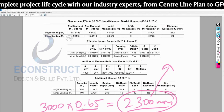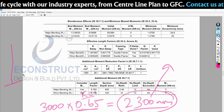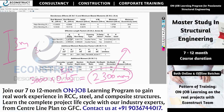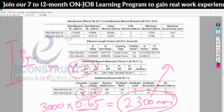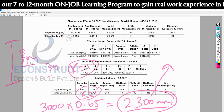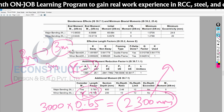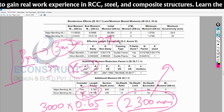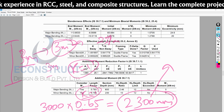Now consider the K value. In any case, it can be 1 only. The actual column is 3 meter only, so you can take the height of the column as 3 meter at most. It cannot go more than 3 meter, correct? It can go less than 3 meter because of the effective length factor, but in any case, it cannot go more than 3 meter. Yes, sir. So that is why we have the upper limit of K as 1 only. If K value is 1, you are designing the column height of 3 meter. That is correct, but actually no need to design for 3 meter. It will be a little less than that, 2.7 or 2.6 meter.